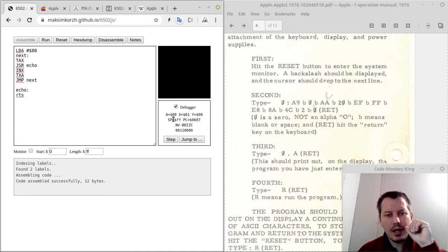So the next step, A would be equal to 1. All right, and so now A is equal to 1, okay? And again, we transfer it back to the X register, then we call this print echo, and now it's going to be printing the next ASCII character. So not the 0 character, but the character 1, like ASCII code 1, etc.